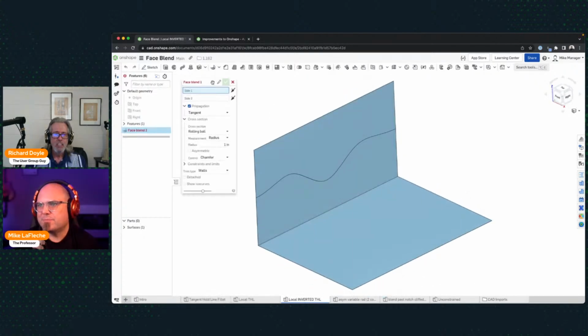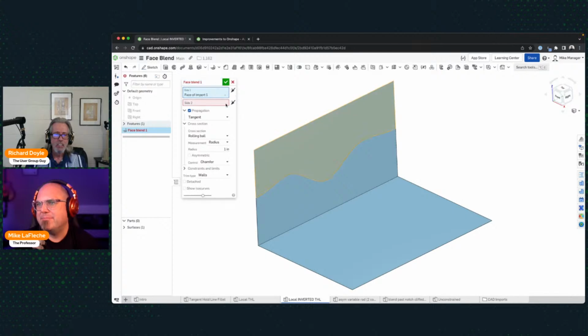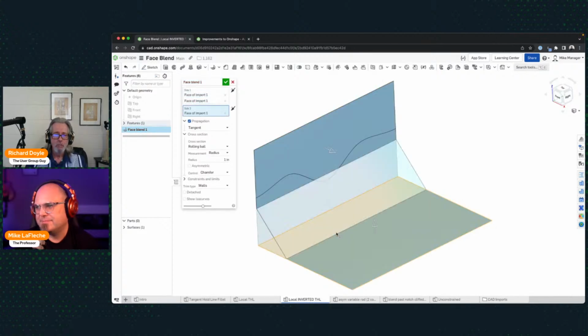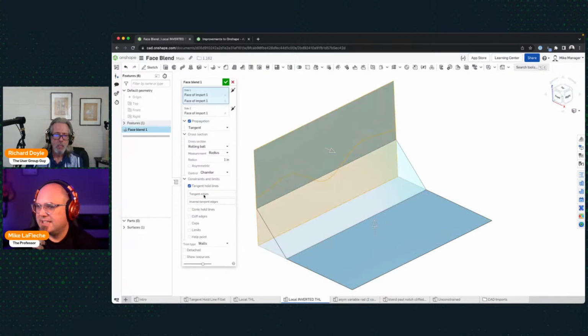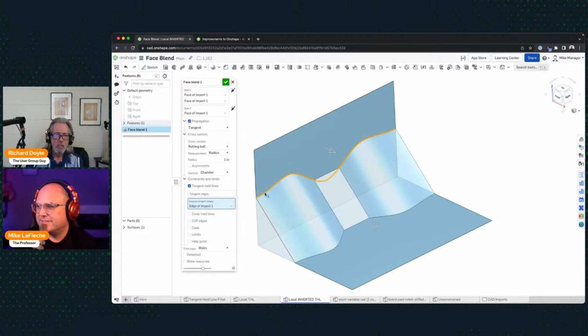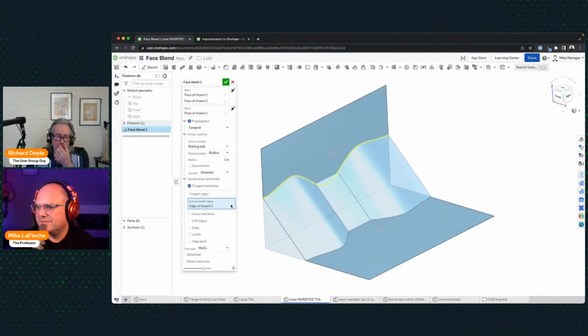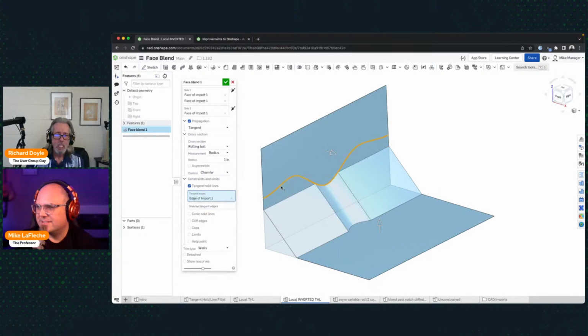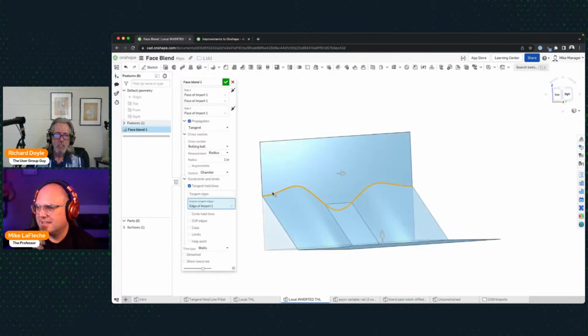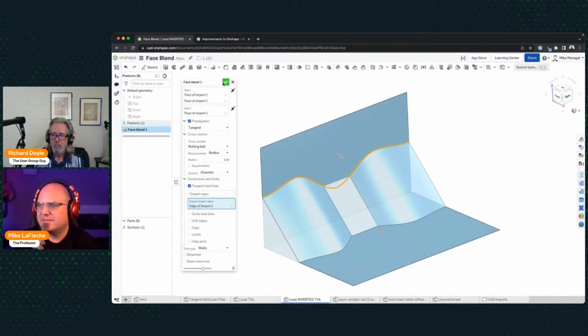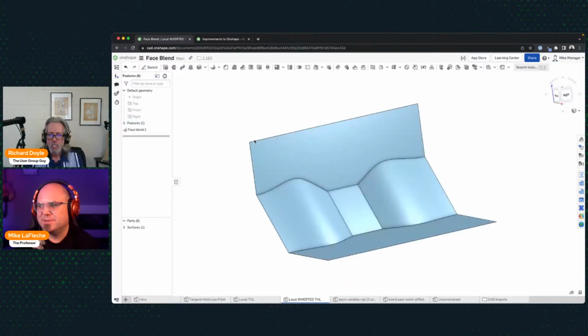So here, I'm going to go to side 1. Side 1 can actually be made of multiple faces, by the way, if it's going to go over that curve that I've split on this face here. So under constraints, I'm going to choose tangent hold line, invert it. There we are. So if we go tangent, it'll show the difference here. That's that inverse. It's just going in the other direction. So that's another way of creating a connection between geometries.